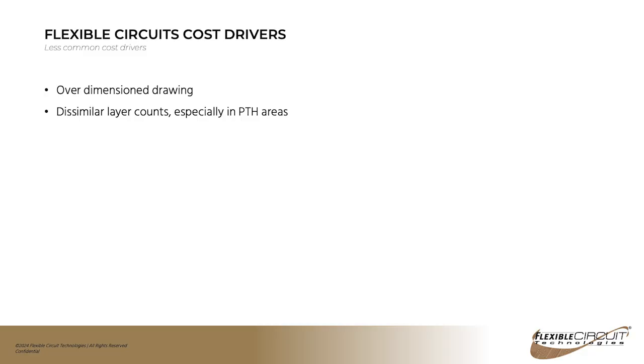You want to make sure that your layer count in each area that has plated through holes is exactly the same. Even if you're just putting pads on those layers, don't try and delete them, because it can be done, but it makes it very, very expensive. A lot of masking is required and a lot of hand operations in order to manufacture that. So make sure that all of your plated through hole areas have the same layer count.